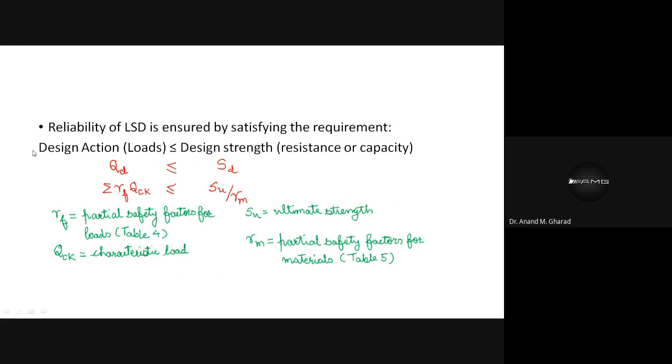This is what is expected in our limit state design method. And while defining this, what is expected is that if we talk in terms of loads, then it should accompany the factor of safety, as well as if we are talking in terms of strength, that is nothing but the capacity of the material or the strength of the material. Over here also we are supposed to take care of the partial safety factor.